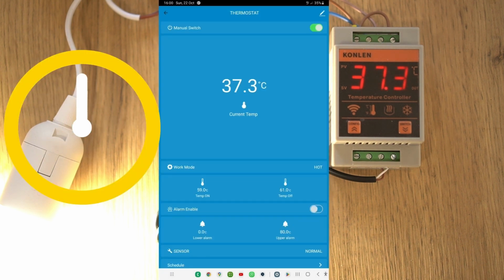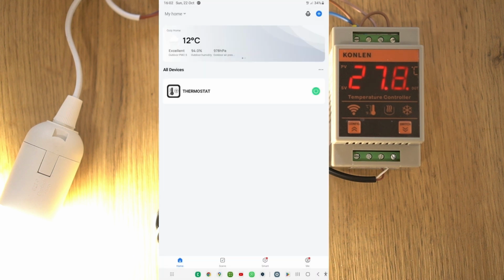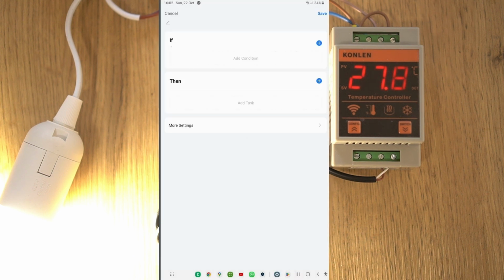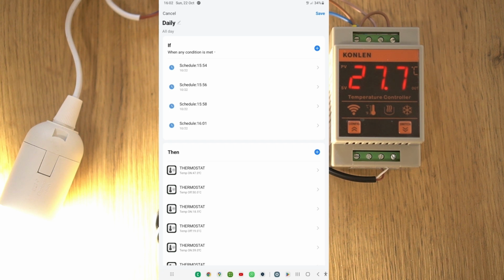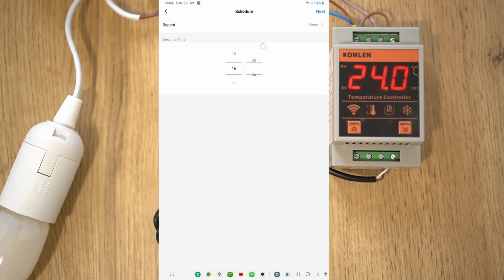So, Monday looks like this. The boiler switches on at 16:07, heats to a temperature of 65.5 degrees. It switches off and cools down to a temperature of 59.5 degrees. Then we add a new scene, but here we're already making the temperature low.